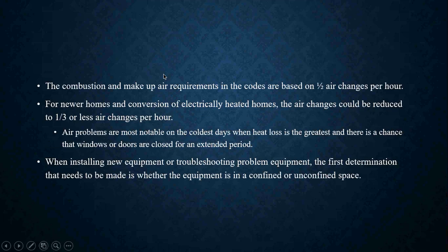The combustion and makeup air requirements in the codes are based on half air changes per hour. So when you look at your NFPA 31, NFPA 54, your International Mechanical Code books, all of those codes dealing with the requirements for combustion air and ventilation base those codes off of a half air change per hour.